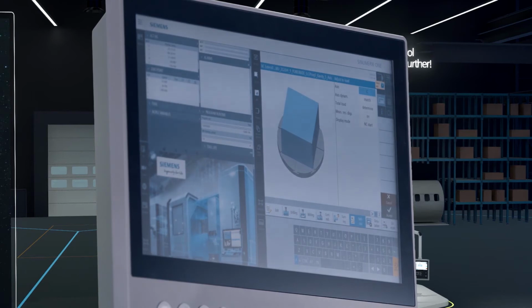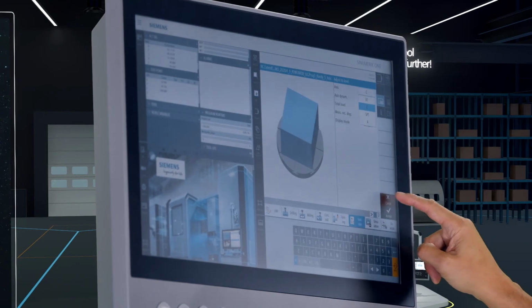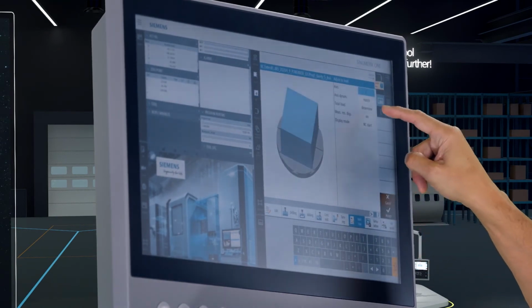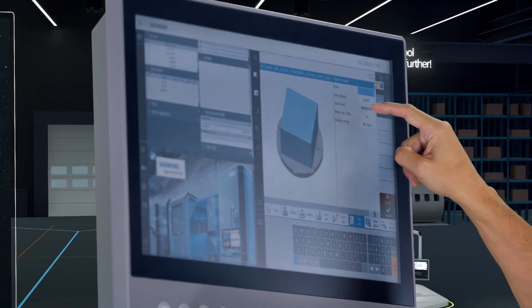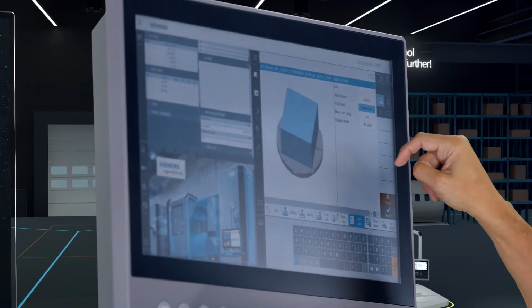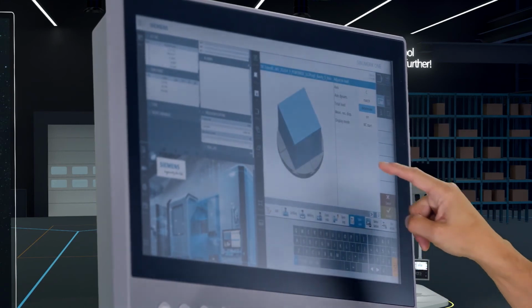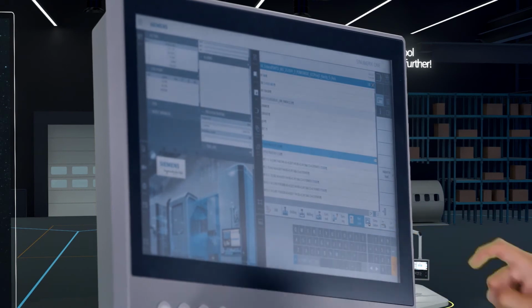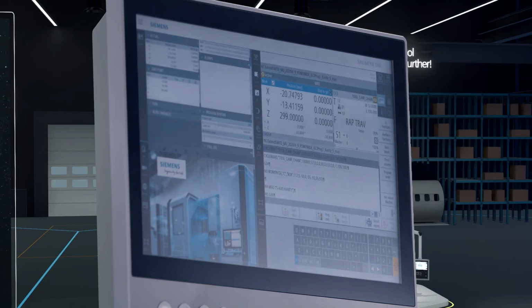With this cycle support screen mask, I have the possibility to adjust the load on any axis defined by the machine tool builder. It could be some linear axis, rotary axis, spindles, whatever the machine tool builder defined. For the operator, we have the so-called axis dynamic adaptation. We have the tool load to determine or to define directly. And last but not least, we have the possibility to show the measured result on the screen. The cycle 782 will be started and I execute the part program, and then just before the real cutting, we will get the measured result.